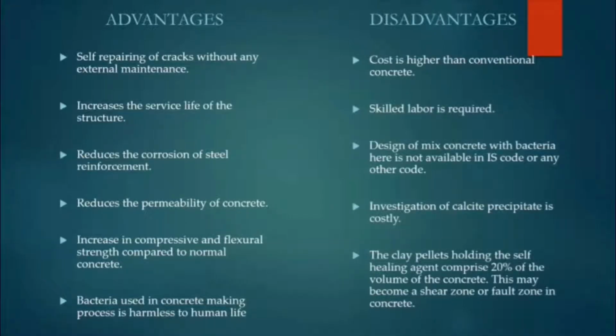Advantages. Self-repairing of cracks without any external maintenance is the most important advantage of using self-healing concrete. It increases the service life of the structure as it will automatically heal the cracks. It reduces the corrosion of steel reinforcement. It reduces the permeability of concrete. It increases the compressive and flexural strength compared to normal concrete. The bacteria used in the concrete making process are harmless to human life.